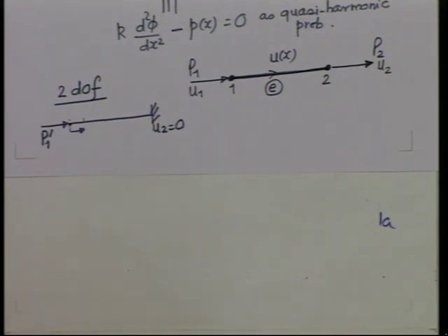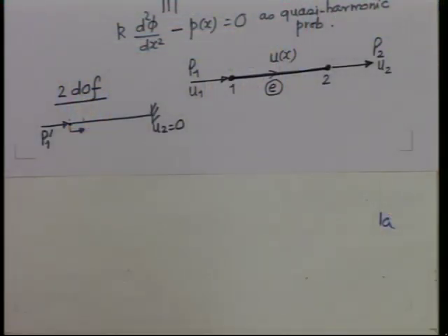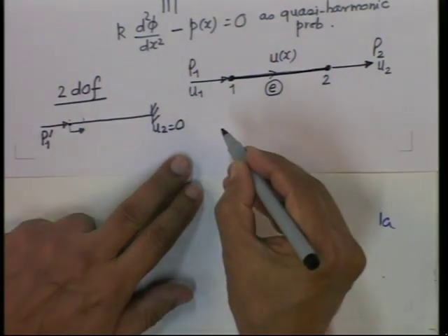That is what is called stiffness. Force required to produce unit displacement is the stiffness of the member. So P1 dash is the force required such that the unit displacement occurs. So, P1 dash will then be equal to k.